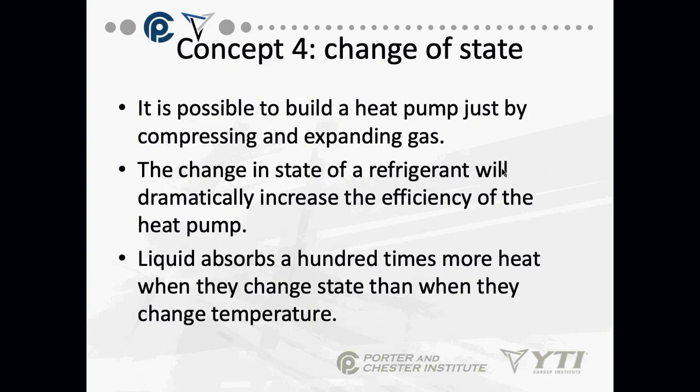Liquids absorb about 100 times more heat when they change state than they do when they change temperature. That's why the latent heat change is so important. Okay, that latent heat change, which is liquid to vapor or vapor to liquid, does about 100 times more heat exchange than when they just change temperature, which is sensible heat. So again, latent heat is the important step of this whole process.